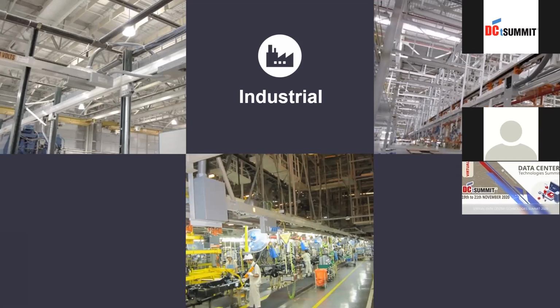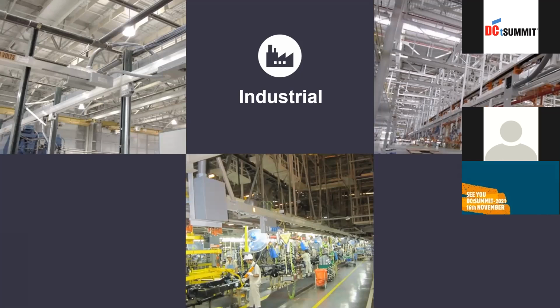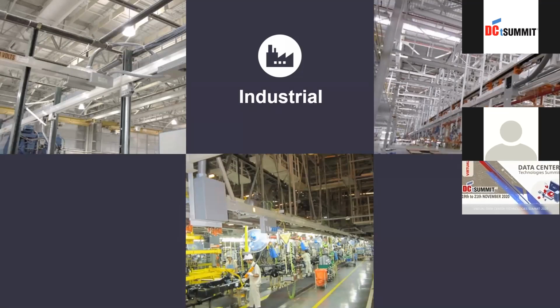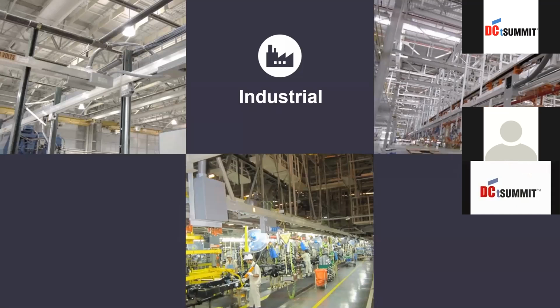So the picture what you're seeing is some of the photos which we have taken from some of our existing customer in the automobile segment, where you can see the bus bars are run along the assembly line and where we're tapping off power to power the various junctions on the assembly line which needs power. And the plug-and-play feature of Starline helps us to remove the tap-off and connect it to wherever you need. So this is a big advantage, especially in the assembly space within the automobile sector.